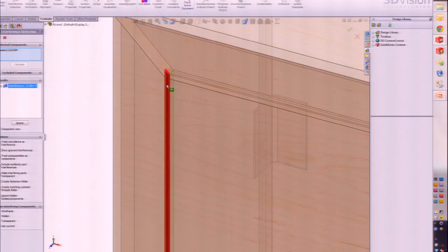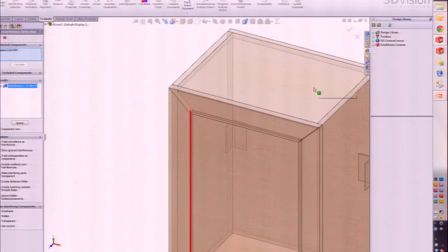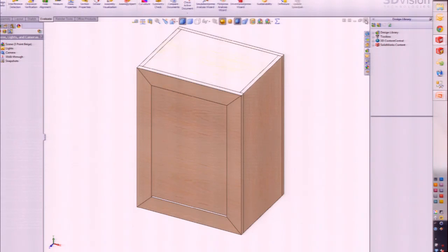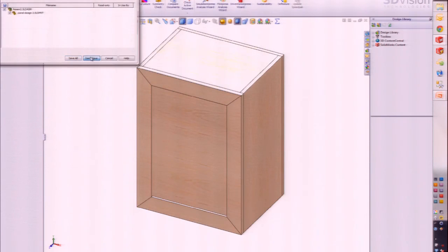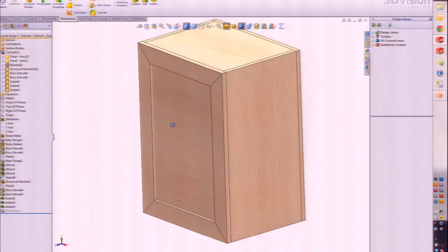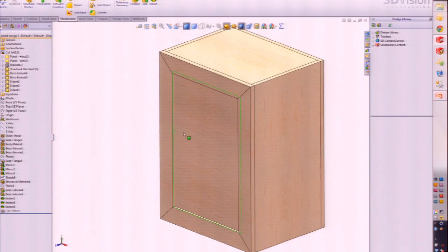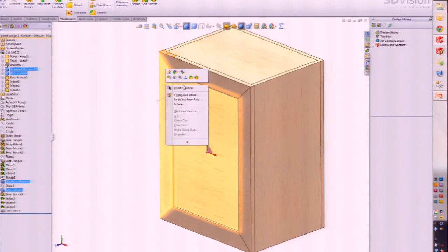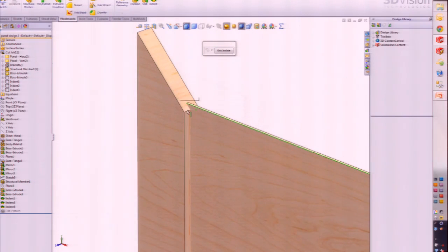Okay? So far, the modeling process of this cabinet is really simple. Just rectangles and extrusions, link to thickness. All right, a simple sheet metal part. Check for interference. The indent feature that I want to show you works like this. I'm going to select these two bodies and right-click and hit isolate. And you can tell that they're intersecting because we don't see that black model edge right there. So that's the easiest way to detect for interference, if you can notice it.